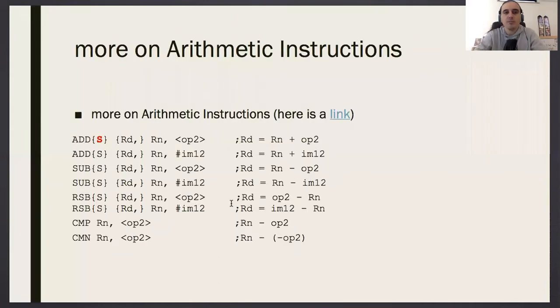Okay, so guys, I'm going to just pour here a bunch of instructions, and you'll realize that they're just simple. This is a notation used to define an instruction. As you can see, it says that this is the ADD instruction. There is an optional S, which means if you put this, it will change the flags so that you could do conditional branching.